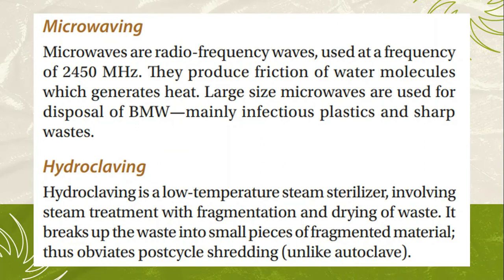Another method is hydroclaving. Hydroclaving is a low temperature steam sterilizer involving steam treatment with fragmentation and drying of waste. It breaks up the waste into small pieces of fragmented material, thus obviates post-cycle shredding, unlike autoclave.